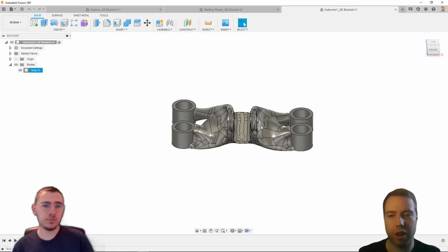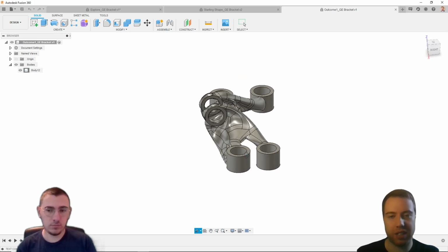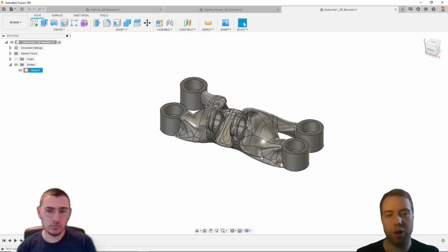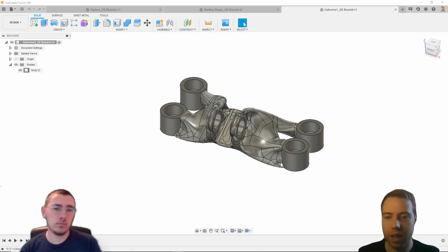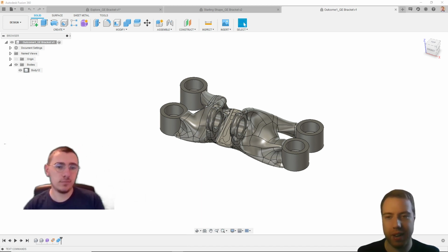I also want to show you, we spoke a little bit in previous weeks about how we can edit some of these designs, and we looked at one of what we call our 2.5 axis outcomes, which is another manufacturing constraint that creates really highly optimized designs, simple designs relatively speaking, that are easy to manufacture with a process like CNC machining. And we talked about how we can go back on the history bar and edit those designs using sketches. So when we have a more free-form design like this,